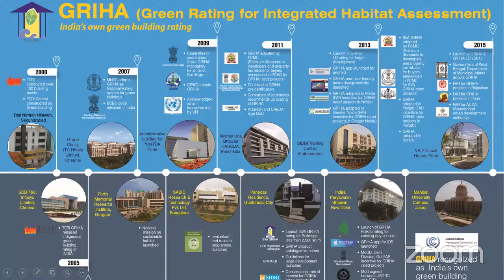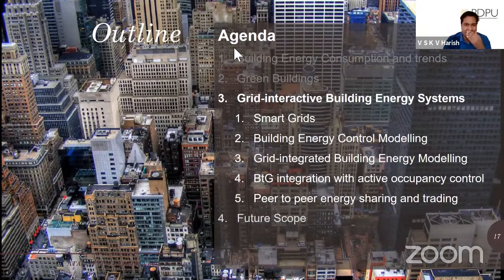Now, having looked into that aspect, whenever we talk about green buildings, the three major points that need to be looked upon are, first, of course, the energy usage, the electrical form usage and the non-electrical energy usage. Second is the waste disposal: how much waste is being created during the construction, during the operation, and also if there is any selective dismantlement of that building, and how efficiently you are using the water as well. So you talk about water efficiency, energy efficiency, and waste disposal whenever you speak of the green building.